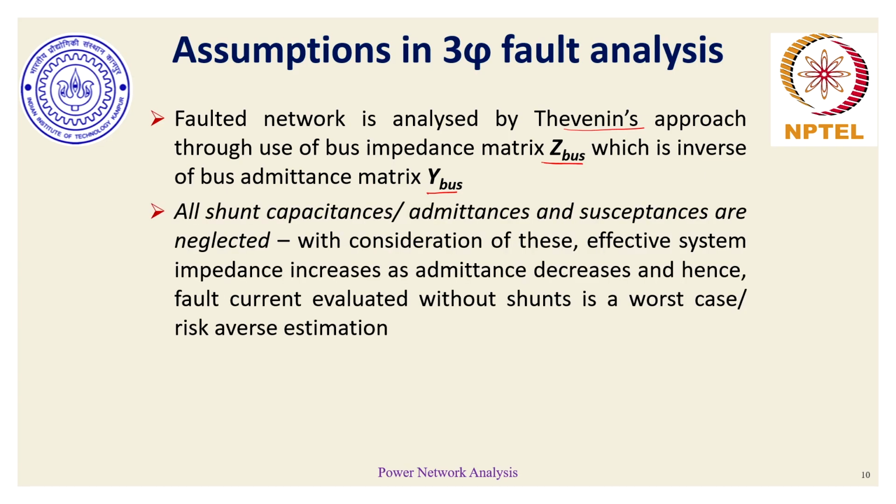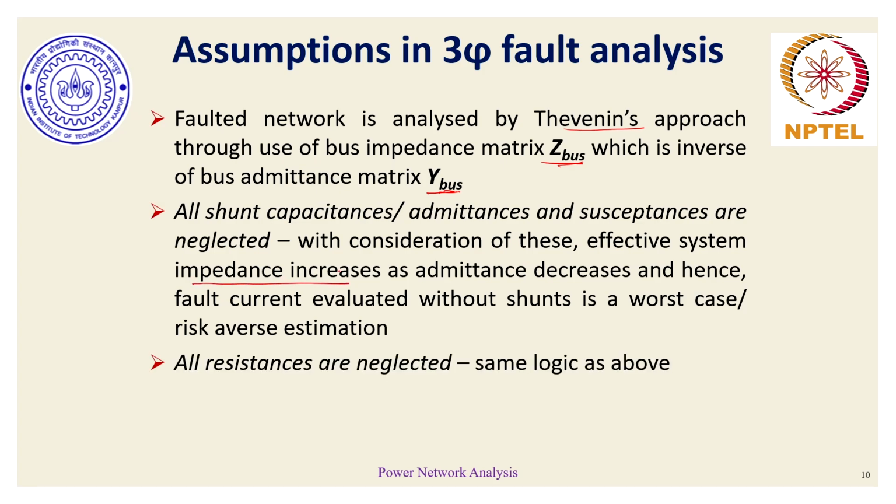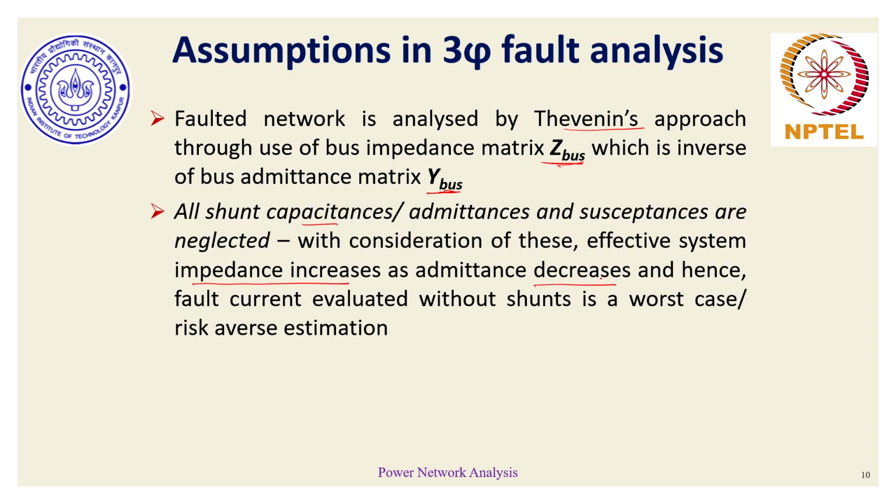Certain assumptions that would help in simplifying the fault analysis exercise is that all elements which pertain to reactive power devices like shunt capacitances, admittances or susceptances, their effect can be considered negligible, their presence can be ignored, because even if these elements were to be considered, while finding the corresponding Y-bus or Z-bus, the overall system impedance would increase in the presence of these elements, and as a result the corresponding admittance would decrease.